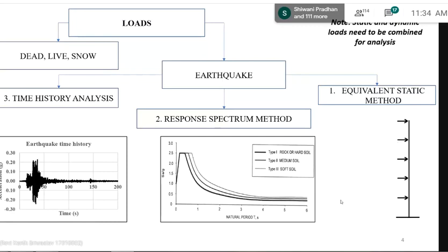Now, if we repeat that for a number of different single degree of freedom cantilever beams, they will have different deflections, right? Because some cantilever beam may have 1 meter height, some may have 2 meter height. Based on that, we can vary the time period of the model, and we can check the peak deformation acting at its top.